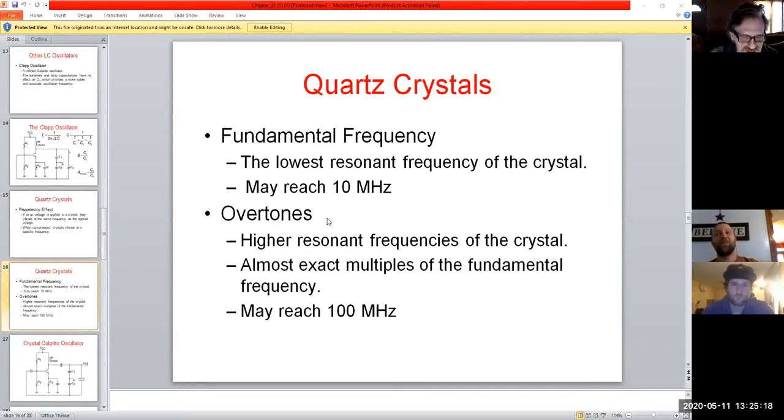And like all the early PCs and stuff like that, at the heart of them they all had quartz crystal clocks. And you could buy them on the market even now, at a given frequency, with a two-lead leg to it, real easy to plop into a circuit, and you are going to get a particular frequency out of it. In fact, my 8088 had the 4.77 megahertz quartz crystal at the heart.